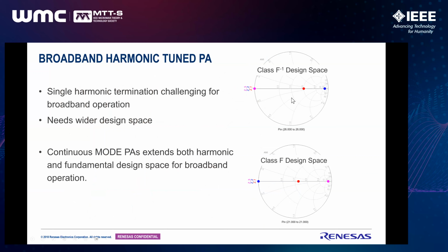Well, the main source of input nonlinearity is its CGS nonlinearity. So when we excite the input of a device with a sinusoidal waveform, due to the CGS and VGS nonlinearity, and based on the termination we are presenting, its voltage can be shaped into different waveforms.